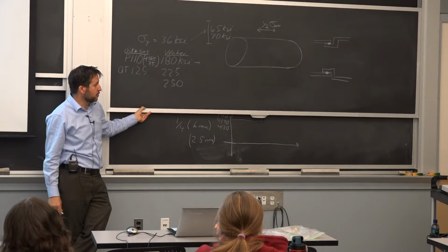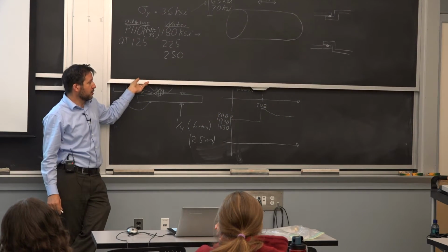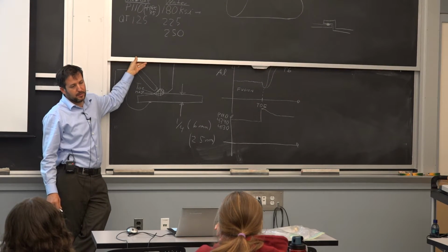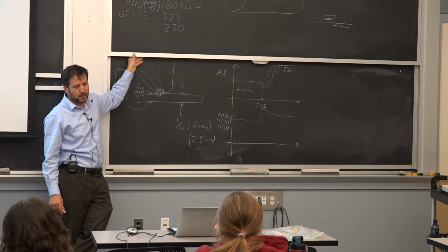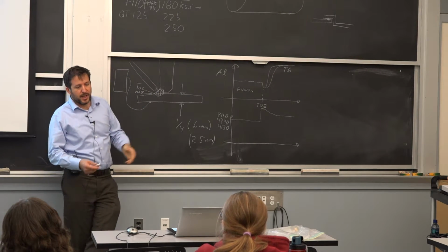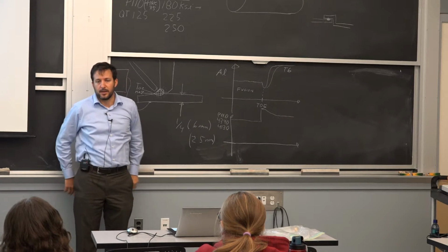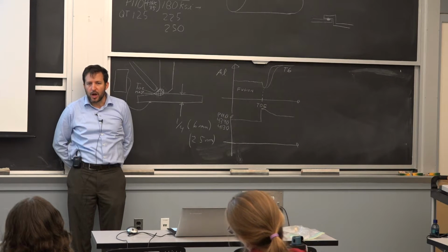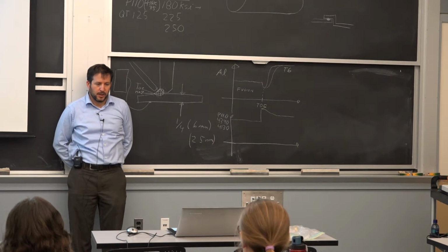It's just essentially very small amount of alloying element that increase the yield strength. Typically by solution hardening. We haven't really talked about solution hardening, but it's another type where the atoms stay in the matrix and just cause friction for the dislocation.